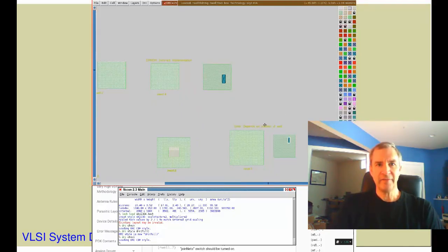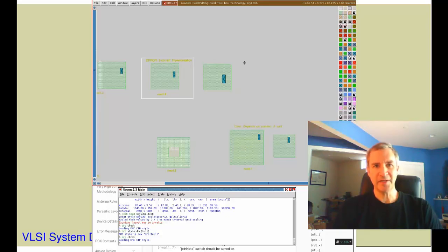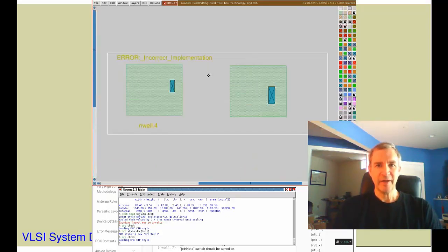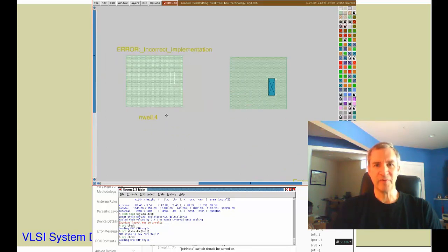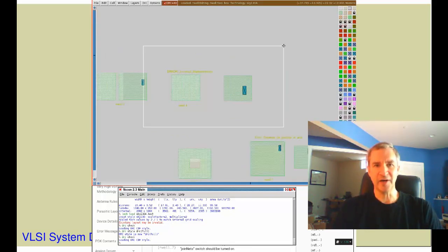Also note that even the Skywater rule implemented in Calibre does not attempt to make an electrical check. Placing a contact in the NWell and not connecting it to anything would violate the spirit of the rule, so to speak, even though it would pass DRC in both Calibre and Magic. It is very hard to implement rules that essentially need to know how a circuit works before it can tell if there's a rule violation or not. Some of this remains up to the designer or maybe to other tools to check and make sure that there are no problems in the layout.